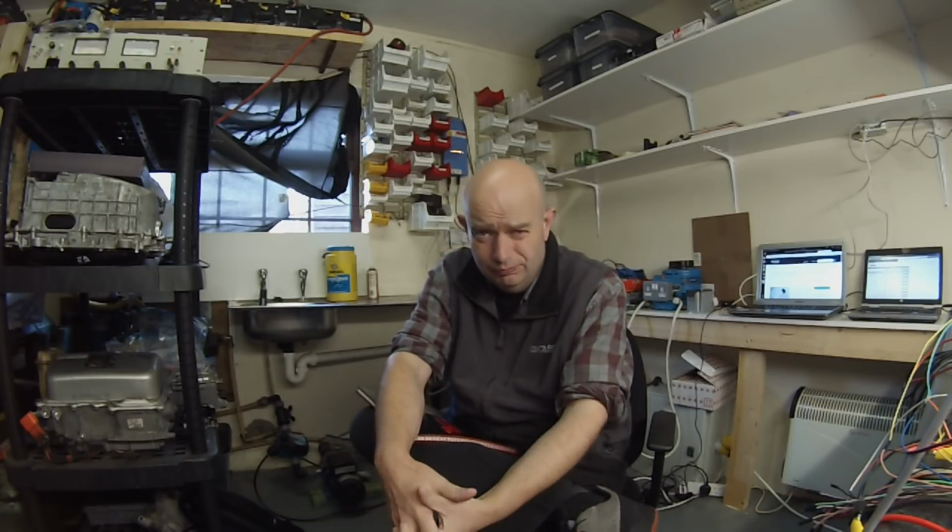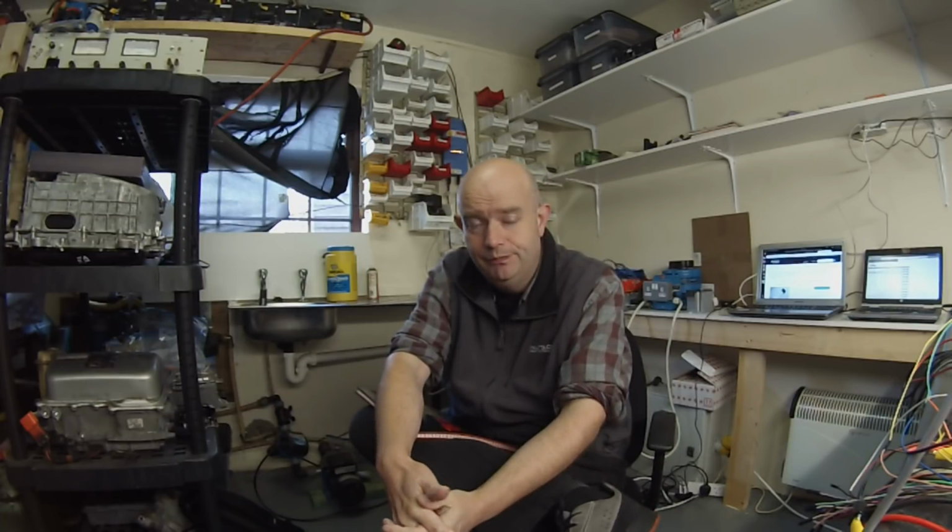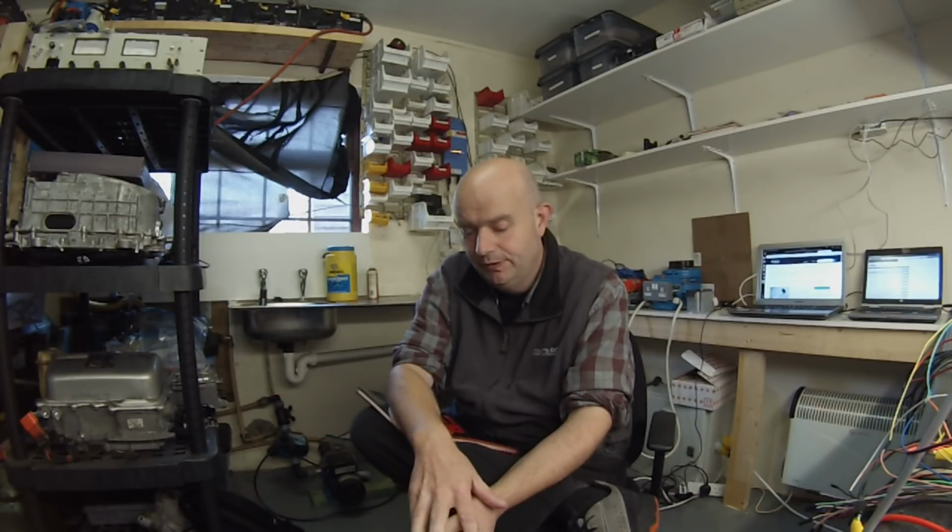I made two immediate changes to the way that we were driving the power stage. The first one was I changed from 8.8 kilohertz switching frequency to 17.6 kilohertz. Quite a big jump, but I'm pleased to report that the inverter works very, very well at 17.6 kilohertz. And the second thing that I did was I changed the trip mode parameter. Now the trip mode parameter lets one do three things.